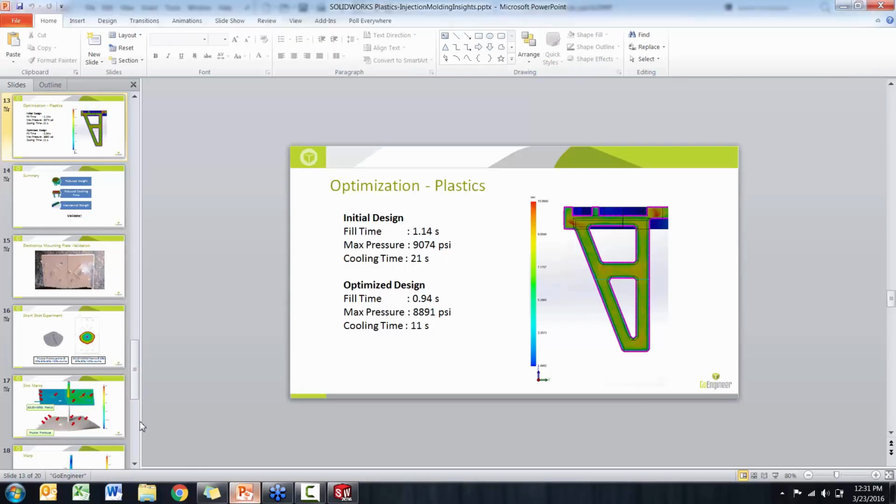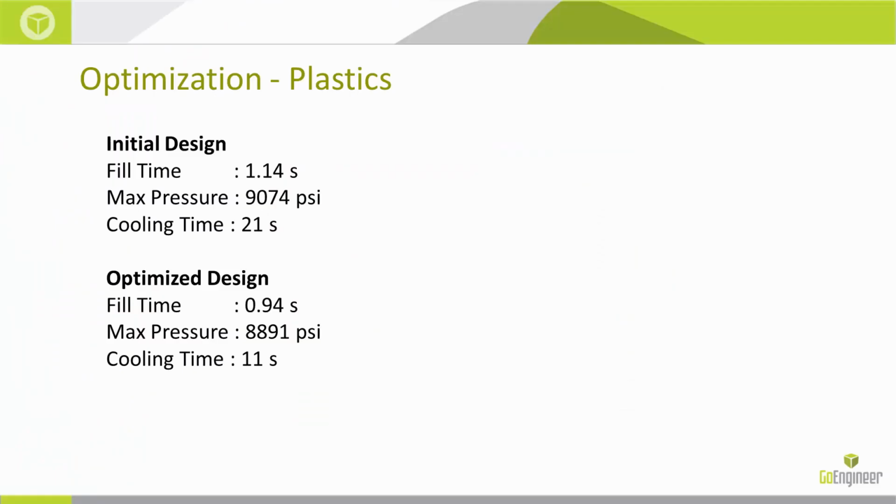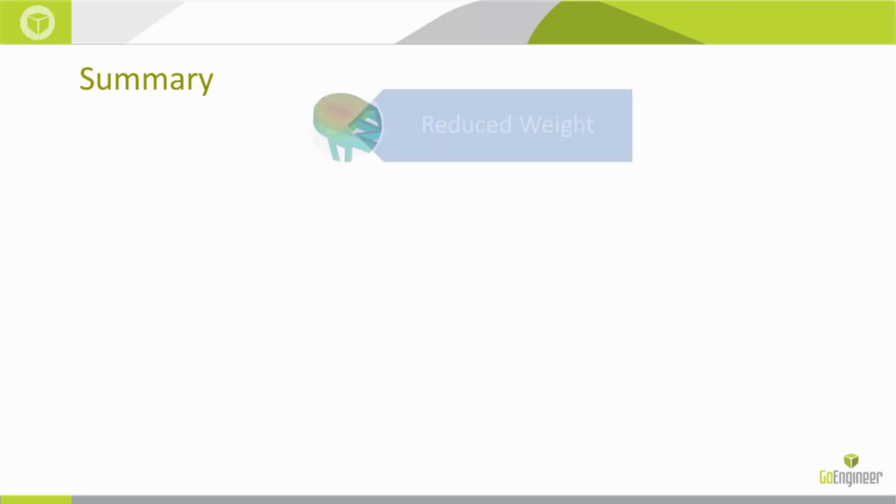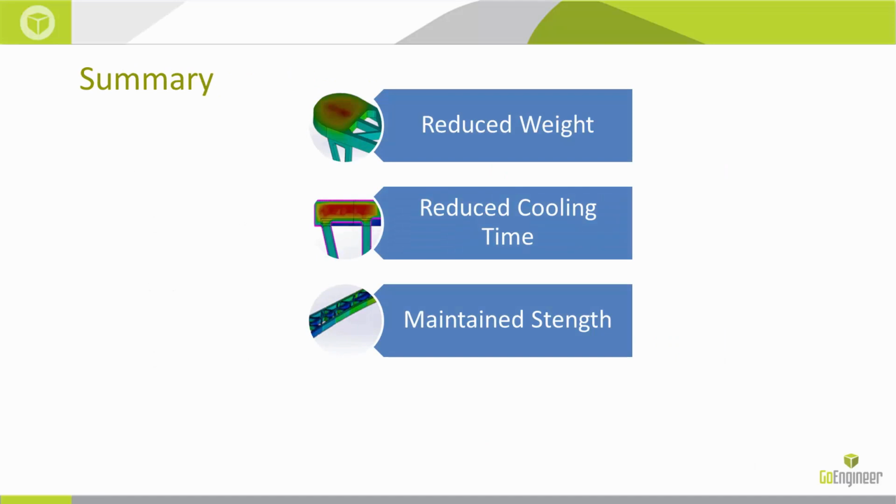Great. Now, jumping back into the presentation to summarize this little exercise. As far as the optimized product goes, here are the results between the initial and the optimized design. So we managed to reduce fill time, the maximum injection pressure, and we managed to reduce the cooling time by about 10 seconds. Now, we've taken a look at how we're able to manipulate our product with confidence in order to ensure its